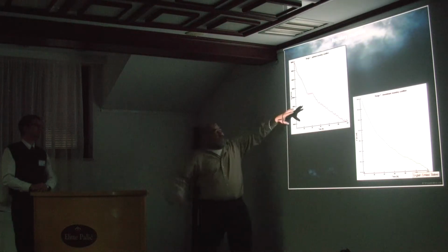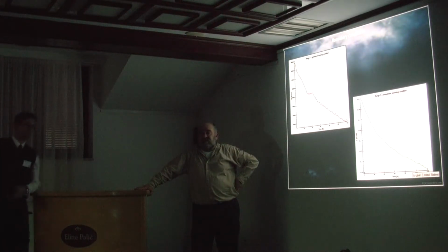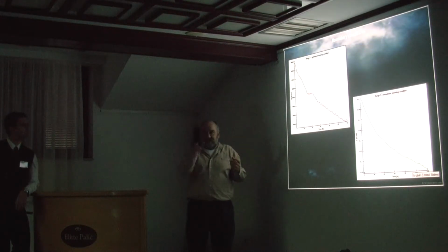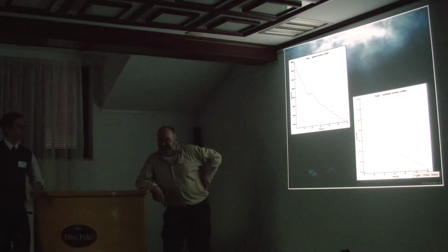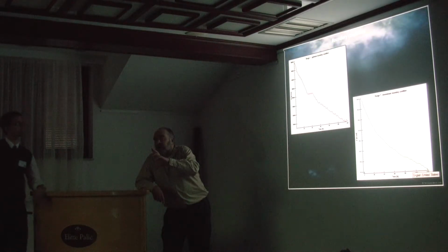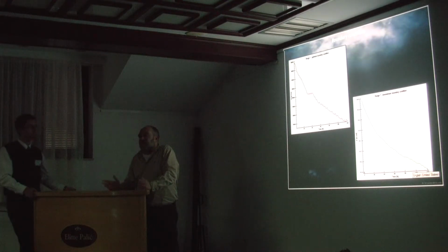For upstream boundary, this is the total discharge that comes from 1D, which means that we have to use some kind of approximation to distribute the total discharge across the flow into unit discharges. And for that we use pretty much our standard approximation that the larger velocity at the cross section corresponds to the largest depth, which is not completely exact, but so far our experience shows that it's fairly close.